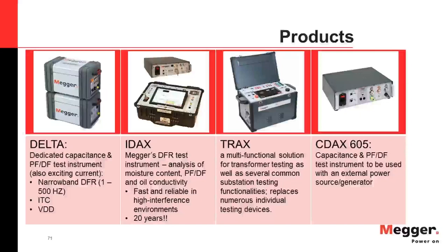But just, if I may add, just one word of caution. In order for winding deformation to show up in capacitance, it has to be pretty pronounced, okay? It's not the go-to tool if you're concerned about winding deformation. If I look at capacitance and I haven't nudged a bit, same picofarads as I measured last time, I still wouldn't put that concern to bed yet.